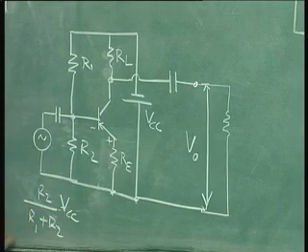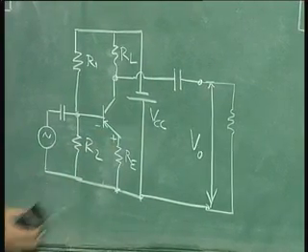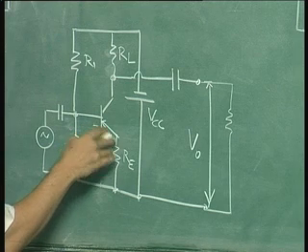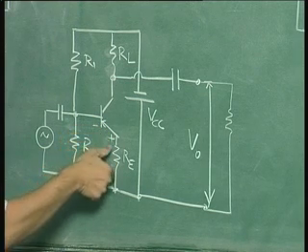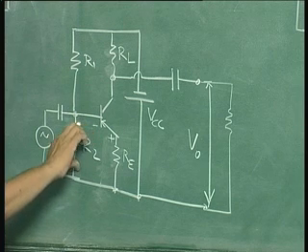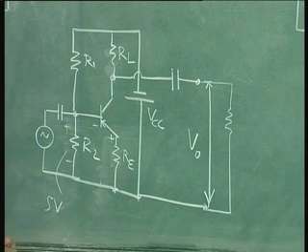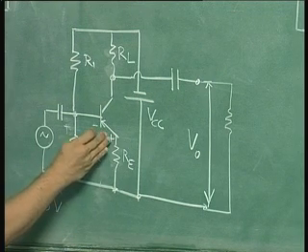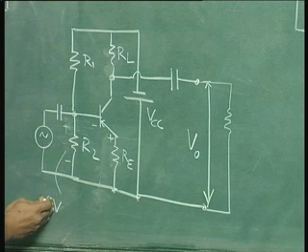Okay, so now your emitter base voltage will be close to 0.65. It may change a little bit because of temperature, but the change will be very small compared to the voltage that is coming here. So if you maintain, for example, 5 volts here, if this voltage is chosen to be 5 volts, then this is 0.65, it may change say around 0.6, 0.7, even if it changes that much, it is not much of a change compared to 5 volts.